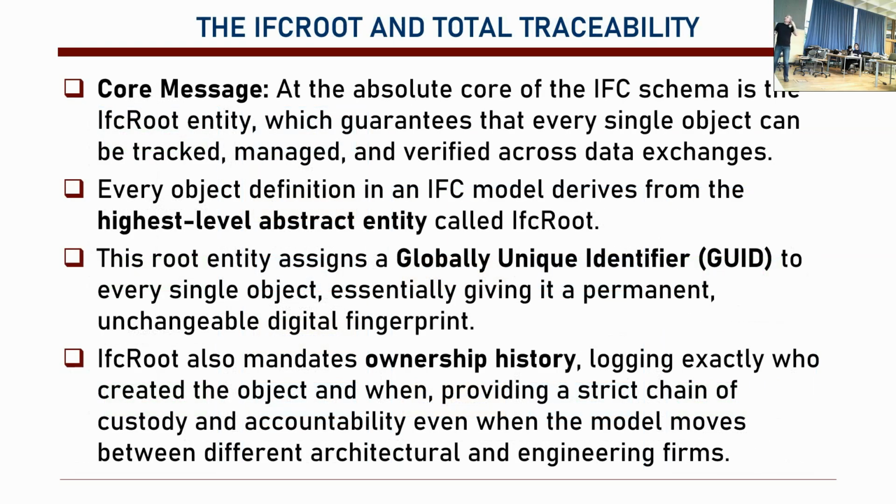Okay, and we have this concept of IFC root. The IFC root entity makes sure that at the root there is one object that is globally, uniquely identified. Okay, so that is the idea. This is the highest level abstract entity, IFC root. So you say that I have an object. First you give the ID to the object, then you describe the object. This object has this geometry. This object is this rectangular geometry like that. And this object is a door. You continue describing it from the root. Okay, this is how you do it.